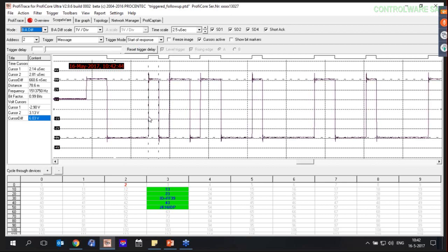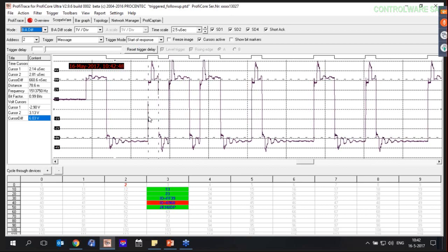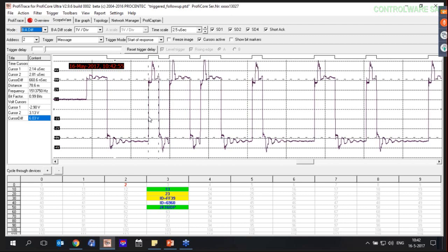This one, I think. You see that if I create a problem on my Profibus, I can see a bad signal on my Profibus. So these are not square block pulses anymore. Again, if you want to find out what kind of problems this is, and if you want to see what the distance is to the problems, please follow our troubleshooting and maintenance training, because we can explain you everything you want on Profibus troubleshooting.